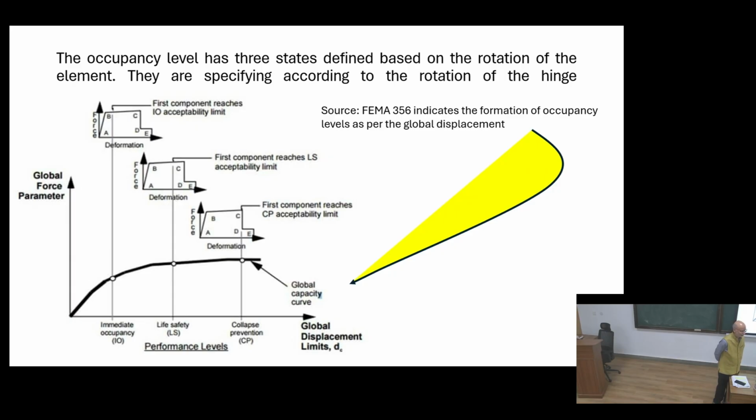How come? UTM? Yes, sir. So you pull it. What happens? Neck formation takes place. How do you define the neck formation? Load is almost constant, not much different, but your elongation is very large. And depending upon the material, the failure will happen.